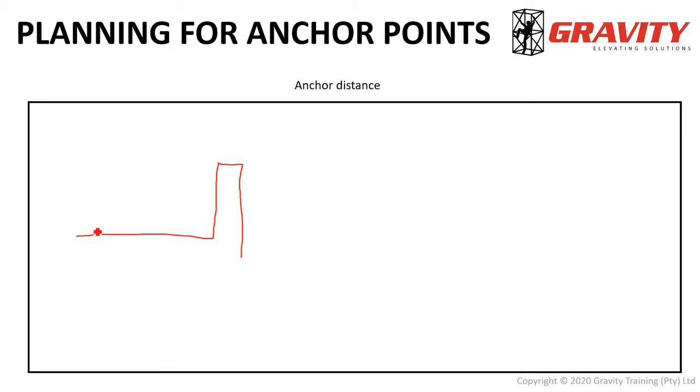So if you were to use, say, a hanger, and you were to place it here, and you had your ropes anchored, and they go over this parapet wall, and you're working there. You see that angle there is quite small. Okay, so the further back you go, the smaller the angle will become, the closer you'll get to that optimal direction. Okay.